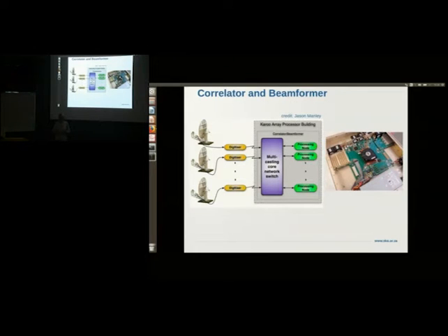For the F engine, there are 3 frequency granularizations that MeerKAT currently implements. There is the 1K mode, the 4K mode, and then the 32K mode. And MeerKAT can also form subarrays. This means that you can split the 64 antennas into different subarrays. You can have, for example, one 16 antenna array doing holography, and another 16 antenna array doing software tests, and the other 32 being used in 32K mode.